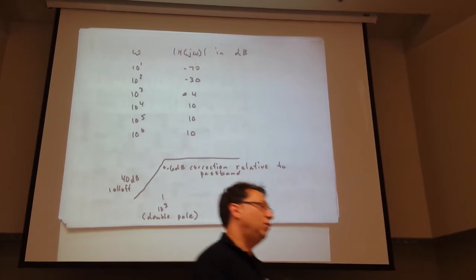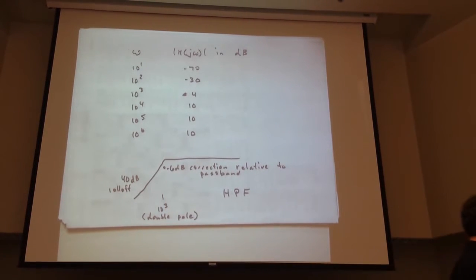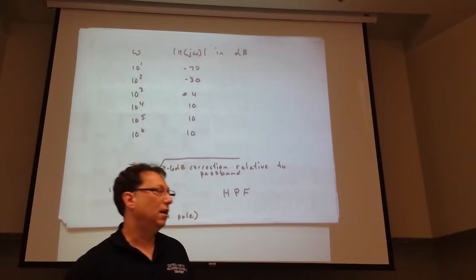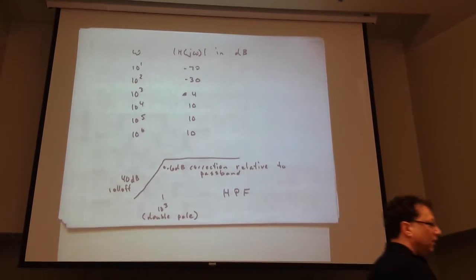That comes back to what we had said previously when we were sketching these things. In the underdamped case, we start with the critically damped straight line approximation, the critically damped curve with its -6 dB point, if it's a high pass filter or low pass filter, or band pass for that matter.